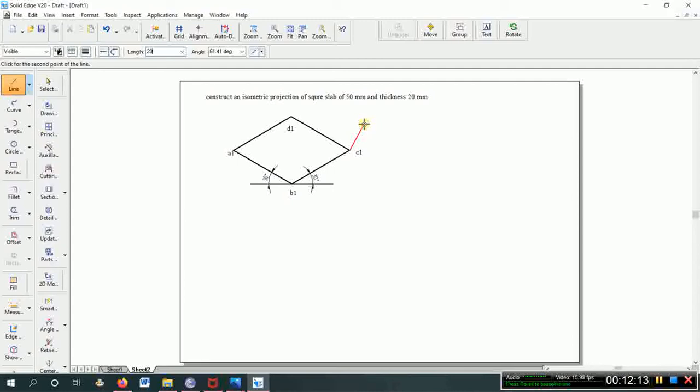So one more thing I want to tell you, 20 mm must be multiplied with 0.816 here also. So whatever the given dimension, 50 mm, 50 into 0.816 I must take. I am constructing on a white sheet here. But if you are using grid sheets in manual construction, no need to convert that to 50 into 0.816. Directly you can take 5 boxes. Okay, so now I have not converted here, but at last I will convert. Okay,